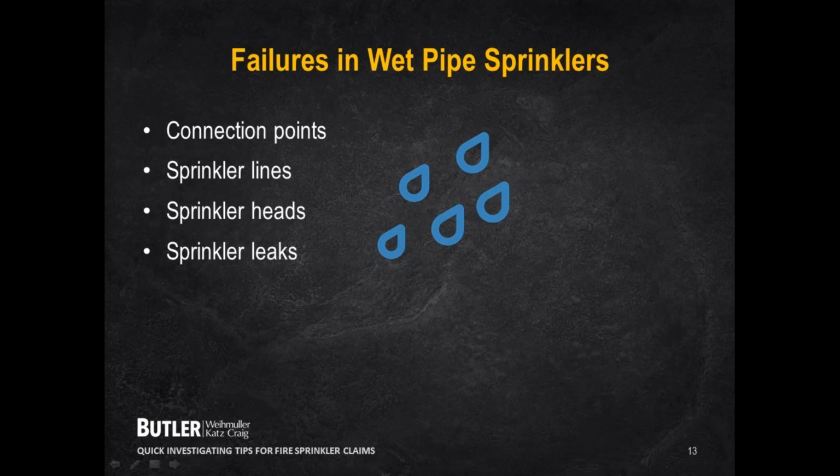I have had one fire sprinkler head loss where a fire sprinkler installer used the wrong temperature head. They used a lower setting of a head, and it should have been for a hotter temperature. So we had a successful subrogation claim against the fire sprinkler installer because he didn't use the appropriate fire sprinkler head.